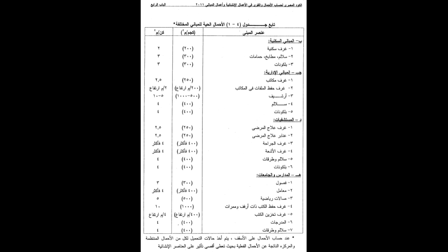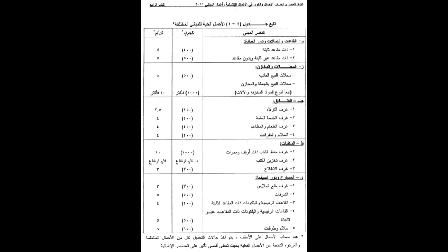Usually when we design hospitals, we get the weight of equipment from the manufacturers. Depends on the design, what equipment will be used, and we get full data of these loads. For stairs and balconies, again, like administration buildings, it is 400 kilogram per square meter.